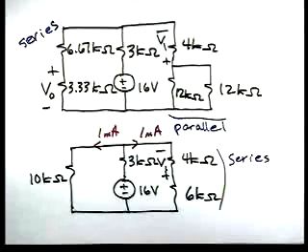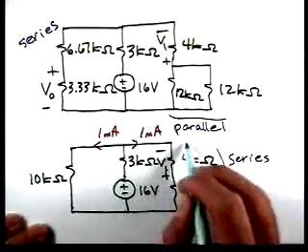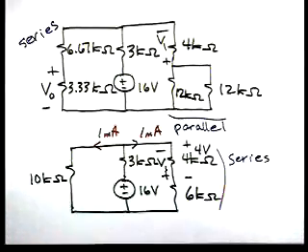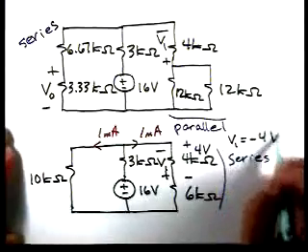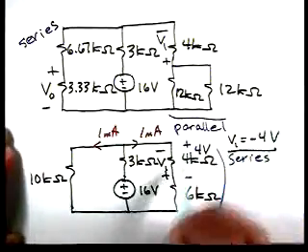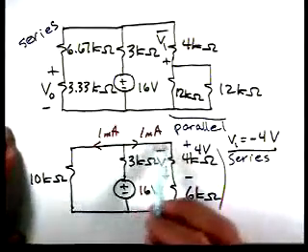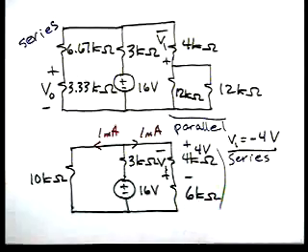If we look at the voltage across this resistor caused by that current, this is going to be 4 volts, okay, and that's from Ohm's law. So then V1 is minus 4 volts because V1 has the opposite polarity of this voltage, and the 1 milliamp flowing in this direction produces a voltage with 4 volts with that polarity from Ohm's law.